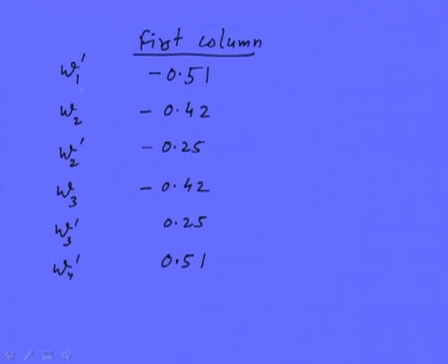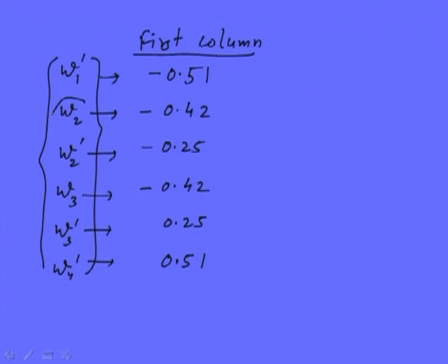You can see that they indicate the values of the vector we had, and for mode shapes we need the displacements. W1 we already know is 0 because of the simply supported end condition, and W4 is also 0.